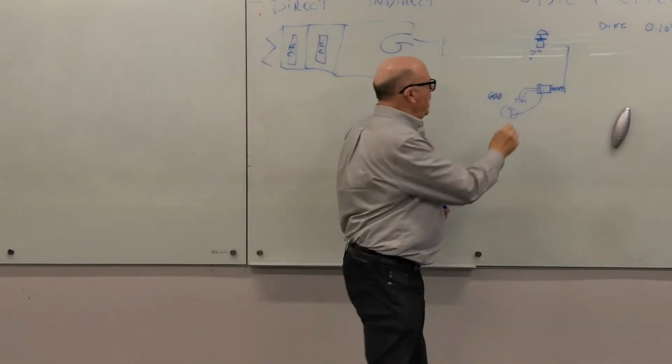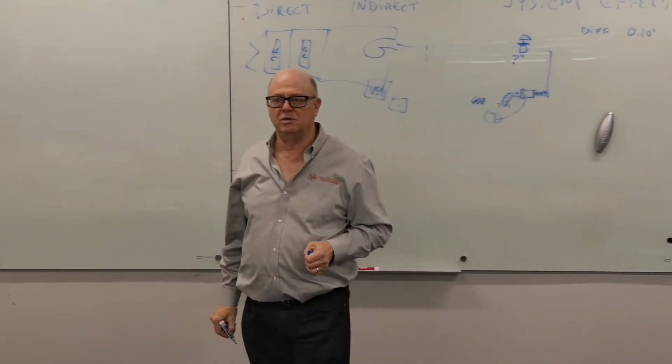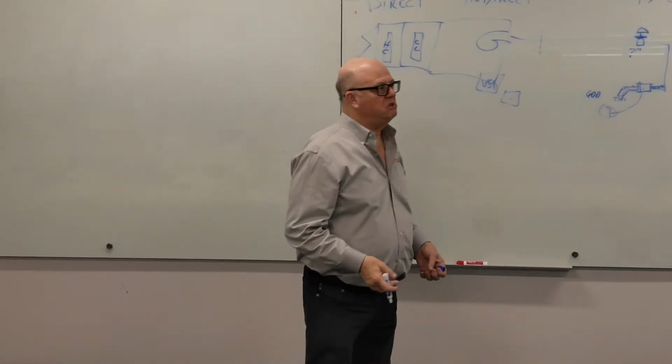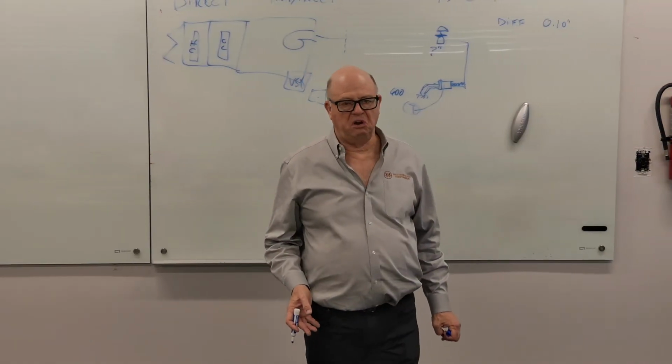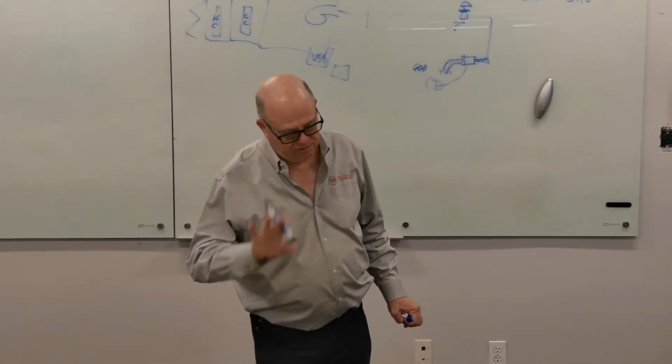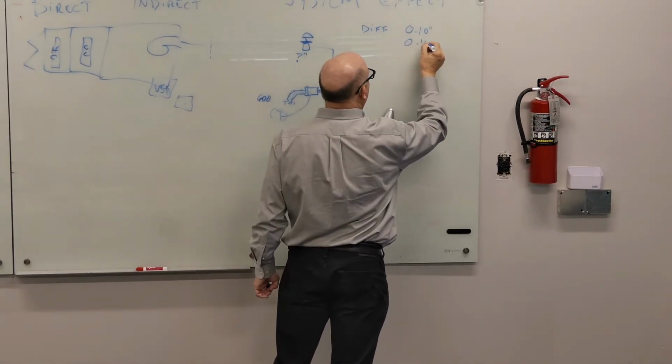Then you look at the flex duct that you've got going back to the VAV box. Is it a short run? Is it a long run? Does anybody really care? Do you just throw an arbitrary number at it? Now we're getting closer to reality. But let's say you did another 1/10 of an inch for the flex.